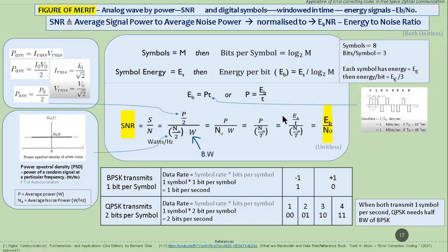for digital communication. A small example: if we have BPSK transmission, the data rate will be 1 bit per second, yes, 1 bit per symbol also. And if you use QPSK, 2 bits per symbol will be sent, and QPSK will use half the bandwidth to transmit the same data which BPSK will take. So bandwidth spectral efficiency is achieved by QPSK, but for long distance, inter-symbol interference errors will cause QPSK to fail. So BPSK has nicely spread signals which will reach further distance than QPSK modulated signals.